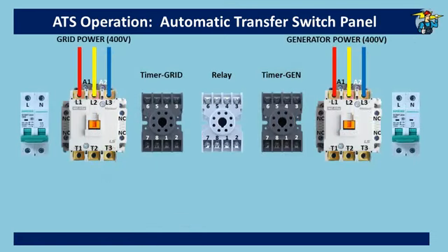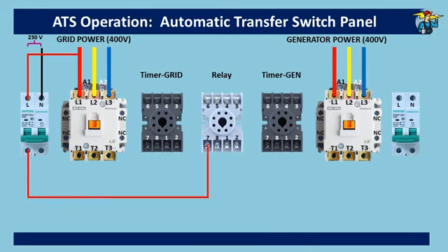Let's take phase line to the grid MCB from L1, and the neutral wire also from the grid supply. The control circuit here is a single phase 220 volt supply. Relay is powered with the supply from the breaker out, connected to the 7 and 2 ports. From number 7, the power line is connected to the common point 8 also.